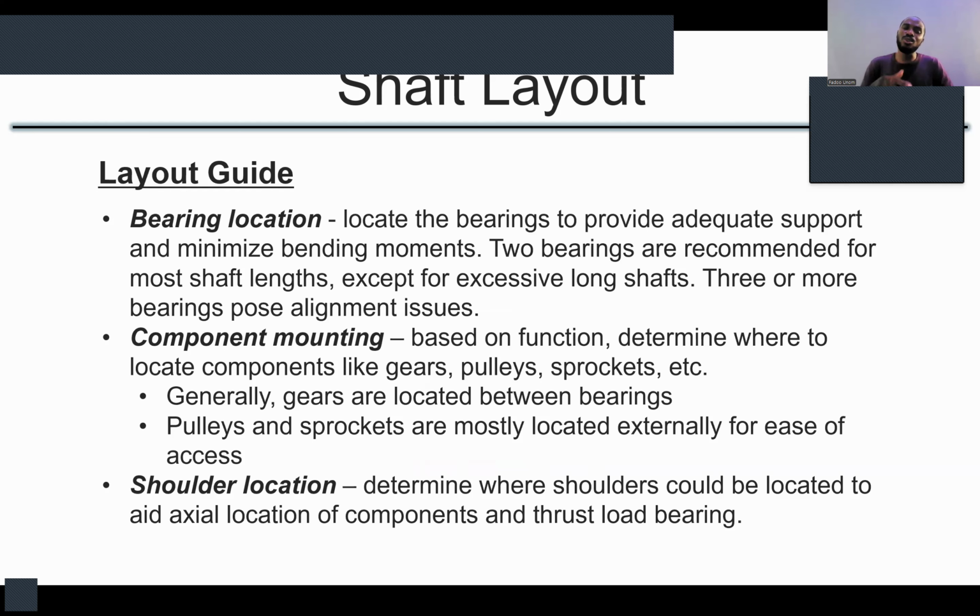Now, where you locate your bearing is very, very critical. You locate them so that you are providing adequate support for the shaft, and you also want to locate them such that you minimize bending moments. Bending moments will cause a shaft to bend, all right?